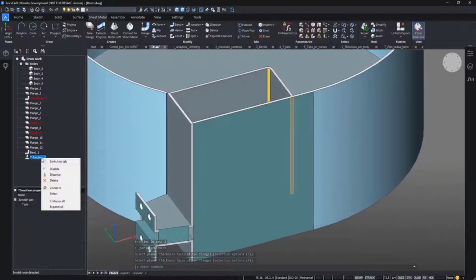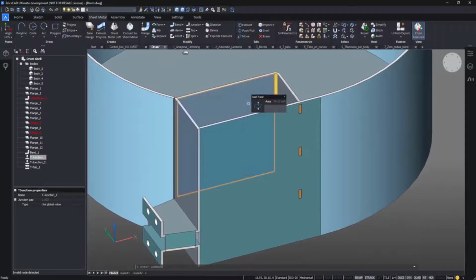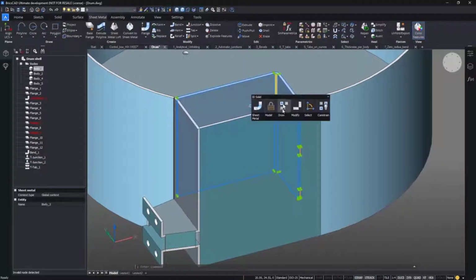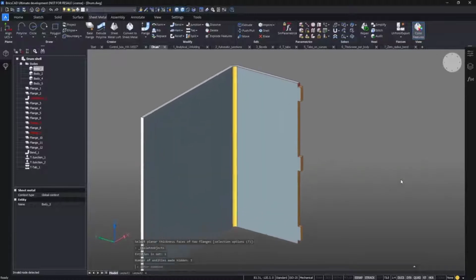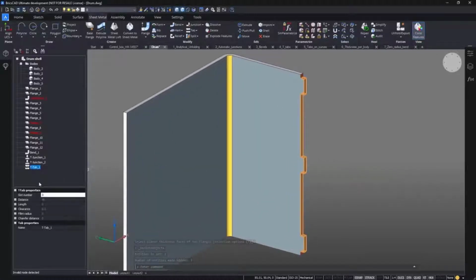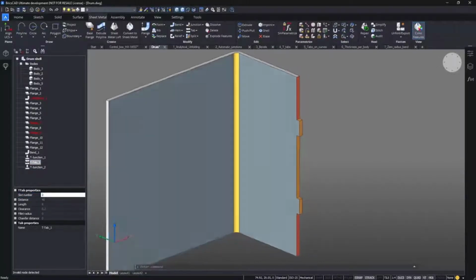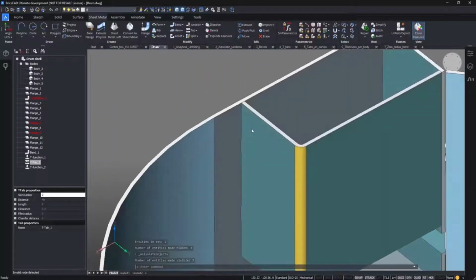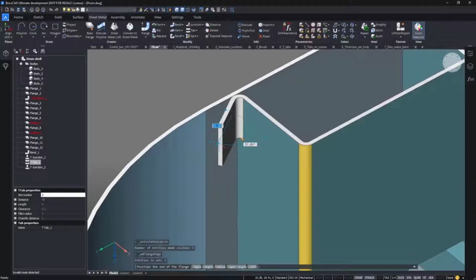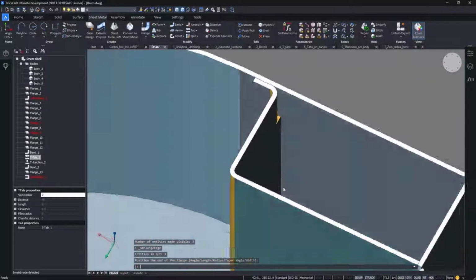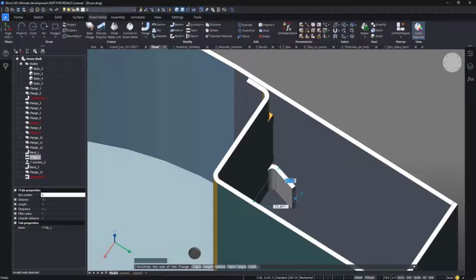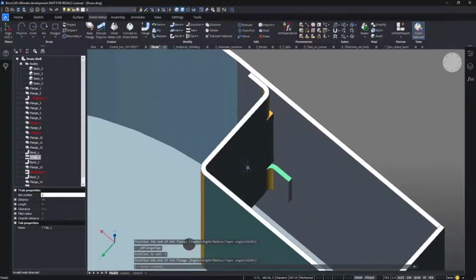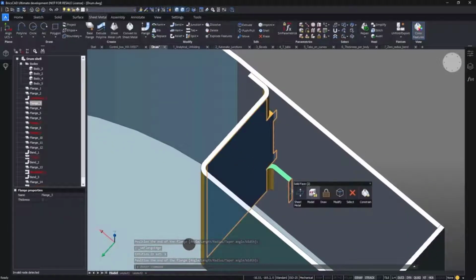Then, with our new T-tab function, we can switch this junction to tabs and slots inside the flange and not only on the corner. Look at the result. And this is editable. We can change any parameter, for example, the number, and it remains symmetrical. Now, we will add 2 small flanges to guarantee the perpendicularity. And we will fix their width.